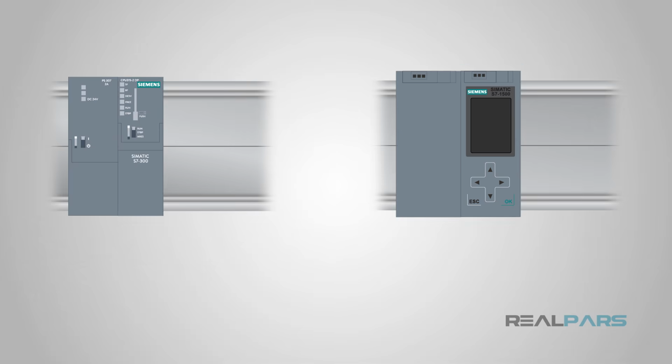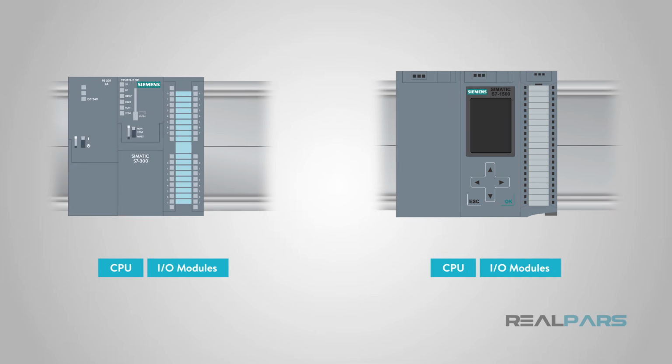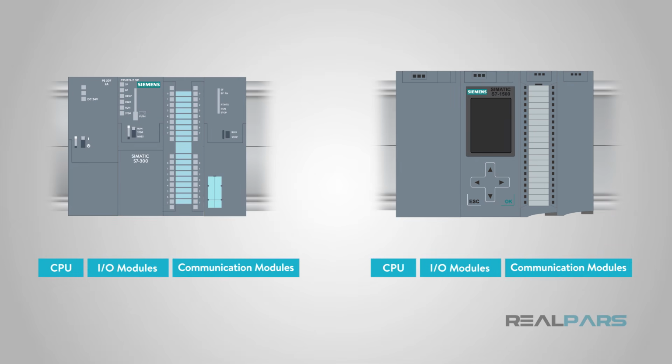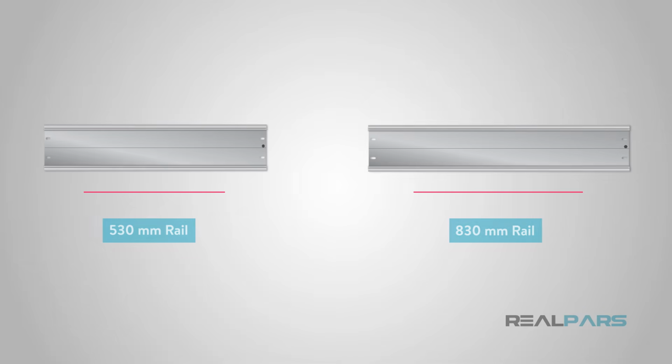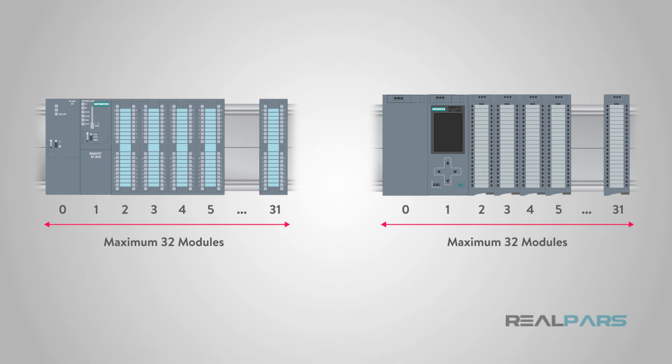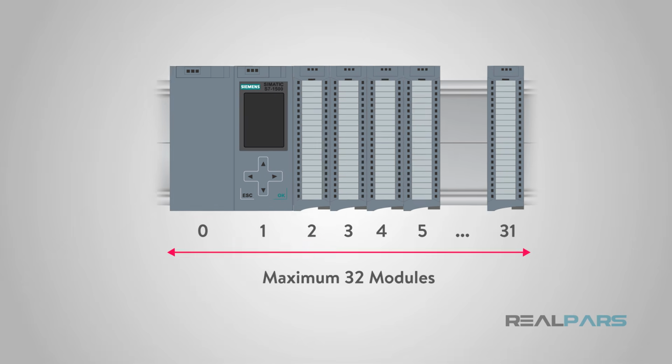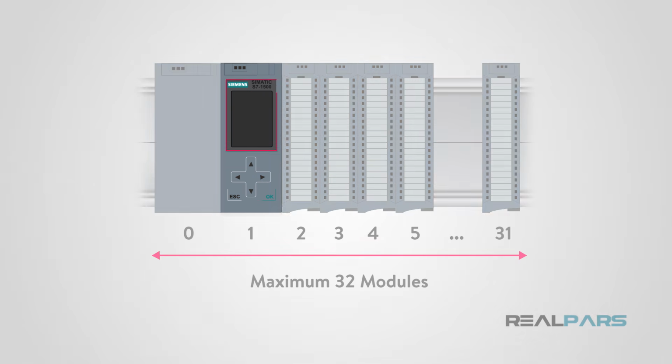Both the S7-300 and S7-1500 PLCs are similar in shape and size, and are built around a modular, expandable design. CPUs, I/O modules, and communication modules may be added as needed to a standard backplane that can be sized to fit your specific project. Up to 32 expansion modules can be installed with both systems, requiring only a DIN rail mount and backplane. The S7-1500 has a standard built-in display and keypad that allows for basic configuration and diagnostics without the need for an external screen.